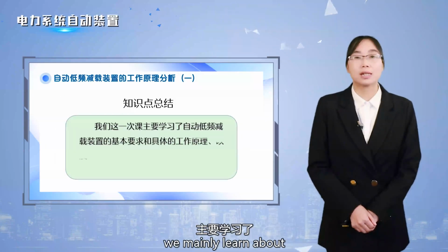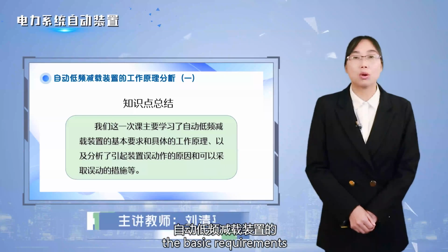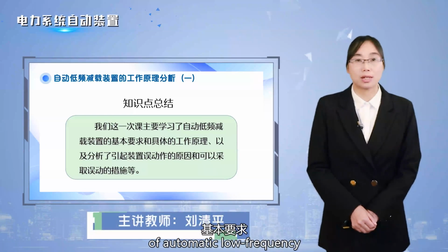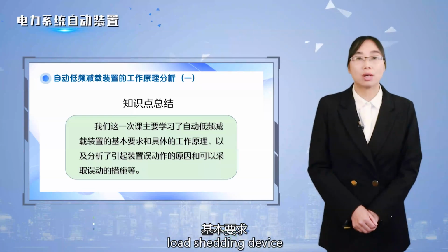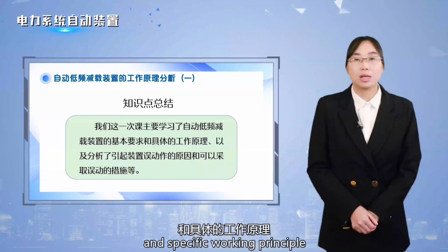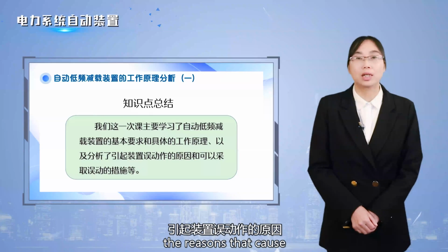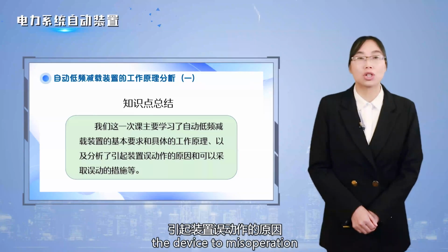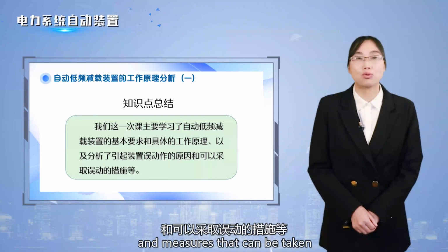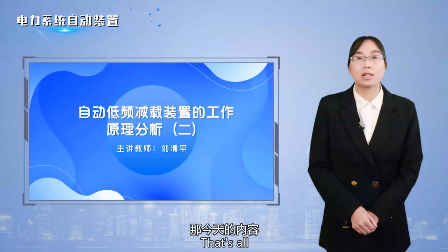In this lesson, we mainly learned about the basic requirements of the automatic low-frequency load shedding device and its specific working principle, as well as analyzing the reasons that cause the device to misoperate and measures that can be taken to prevent misoperation, etc. That's all for today.